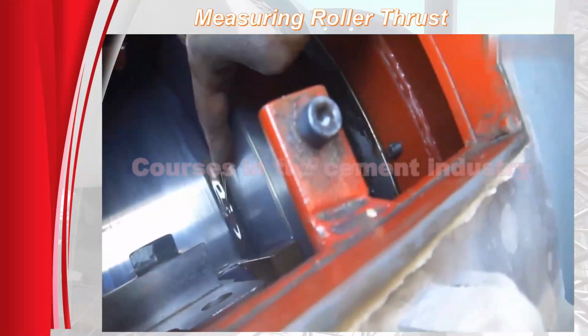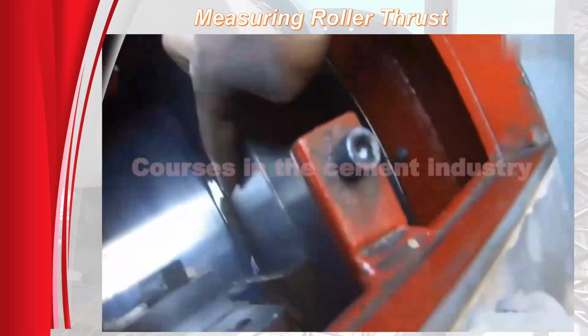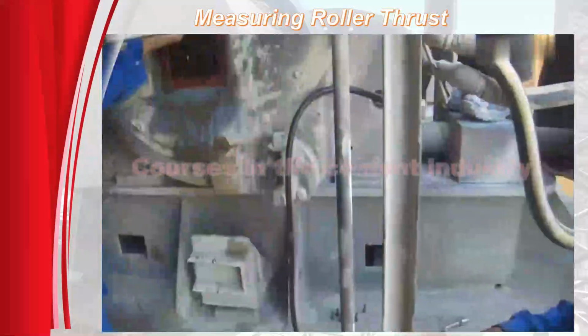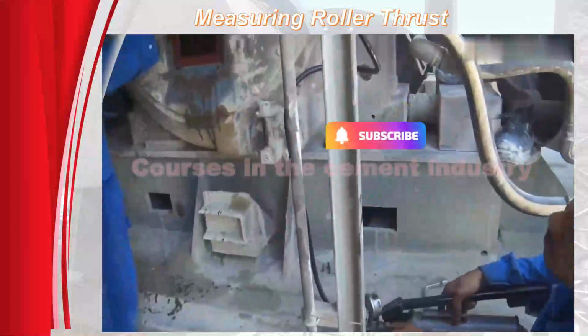Also shown in this video, the jack is pumped up until the roller begins to move uphill, off its thrust stop. At this point, a pressure reading is taken, and the reading is then converted to tons force.